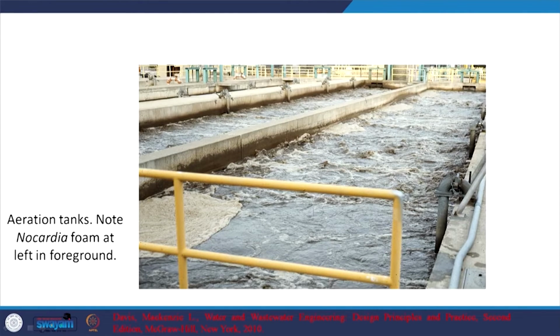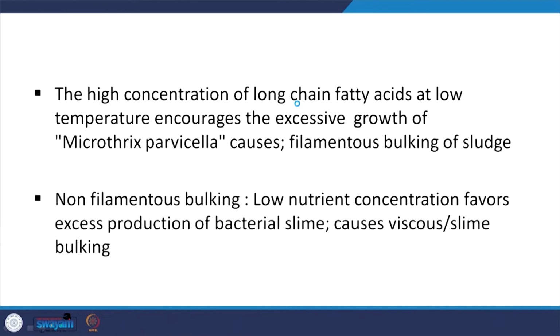Okay, so you can see the foaming out here. That is something that you see. The relevant aspect is high and low: a high concentration of long chain fatty acids at low temperature encourages excessive growth of these kinds of bacteria, which again leads to filamentous bulking of sludge.